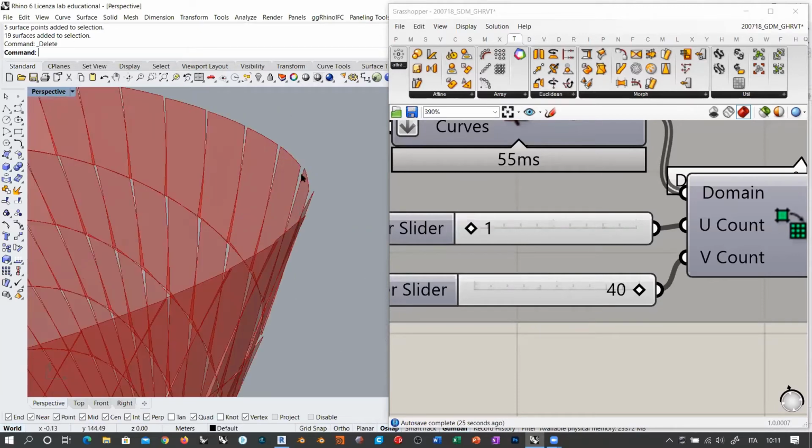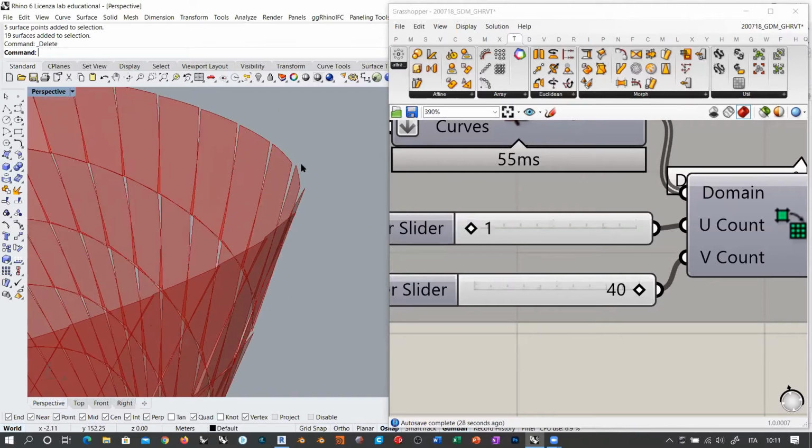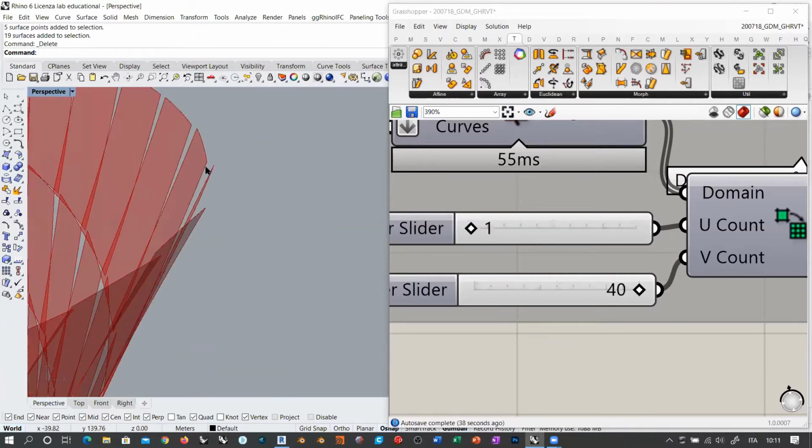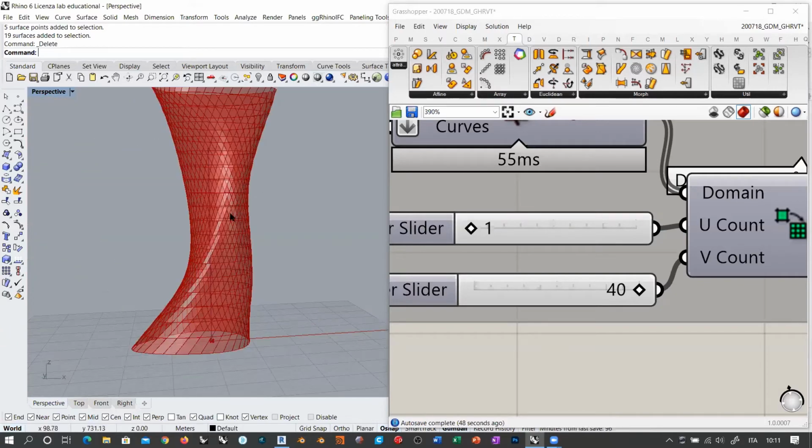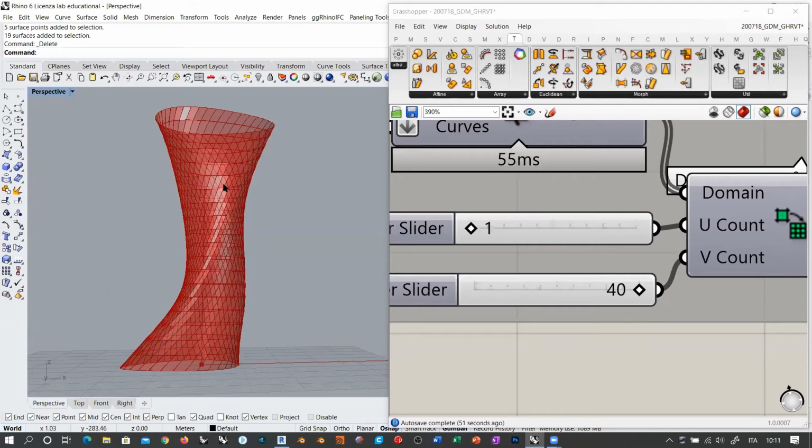Because if you have this kind of deviation here, the structural part of the facade must absorb this variation in the inclination of the panel. So you must use a frame that is capable of absorbing this, or connecting this panel to the other panel. So a thicker structure eventually. Whatever decision you take here, you must take this option into account.